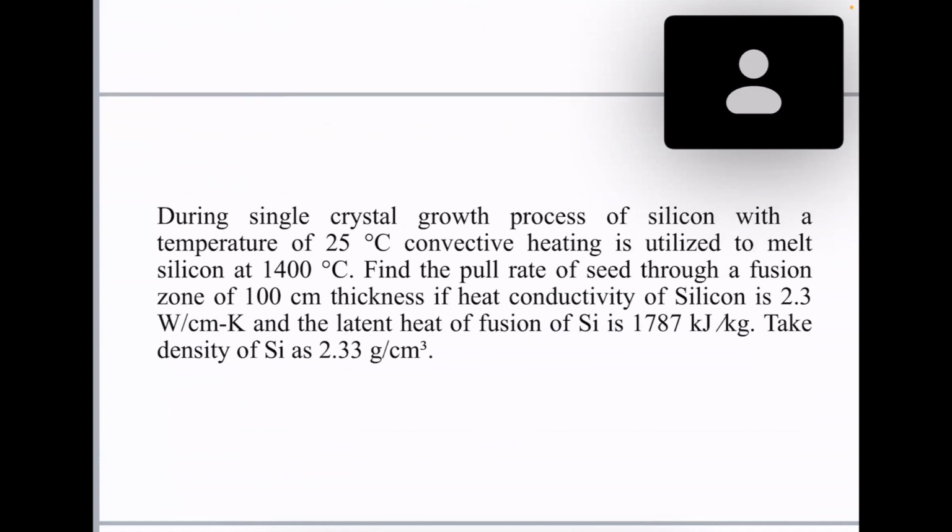Now what happens is, because the melt is there inside the chamber, while pulling it, some extra material gets stuck onto your seed, and with solidification on exposure to ambient, some extra material solidifies, which then needs to be removed again through any wet etching process or something like that, so that you pull out your pure crystal.